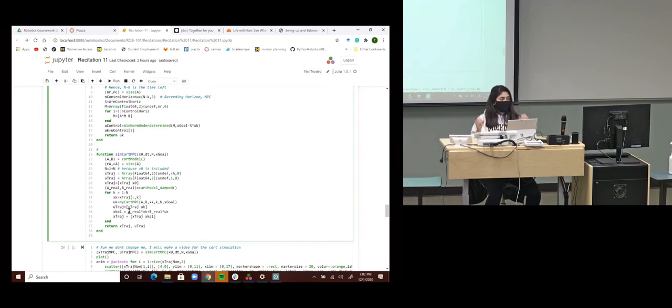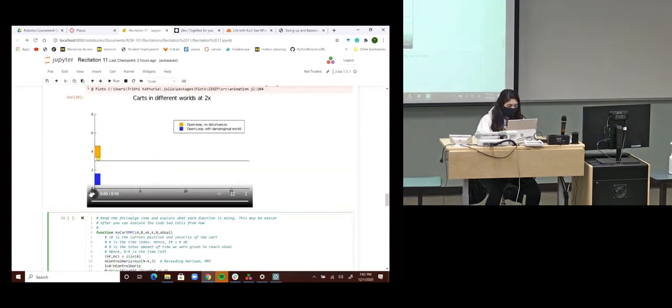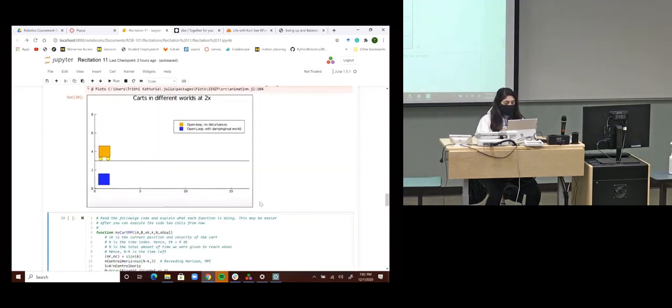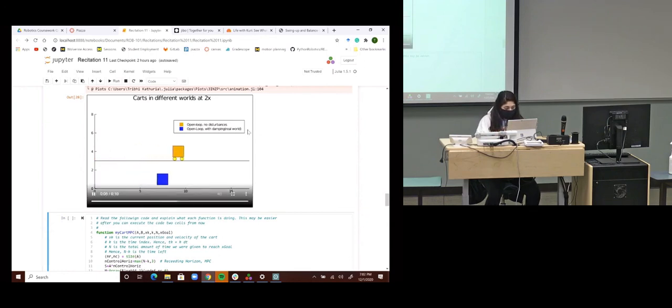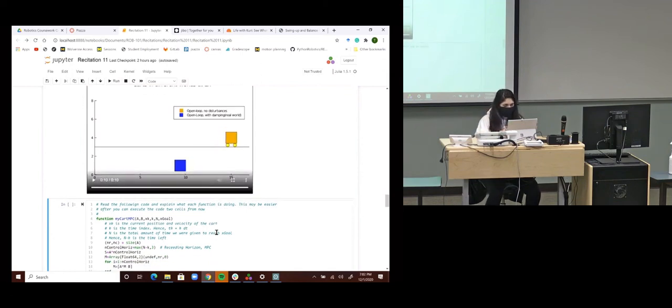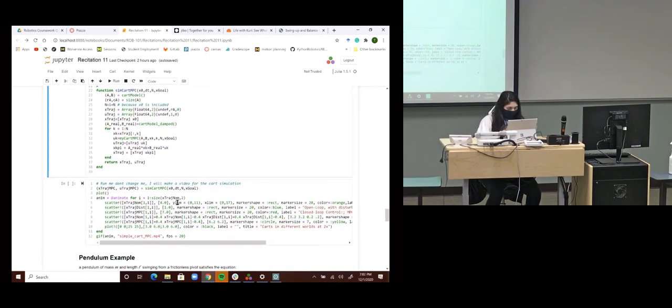So whatever error you accumulated because your model was not perfect, because your model didn't take care of the dynamics, your MPC should be able to compensate for that. So when you were doing it with the damping in the real world, you stopped somewhere around 10 meters. The MPC should be able to take care of that. I kind of went back a little bit also.